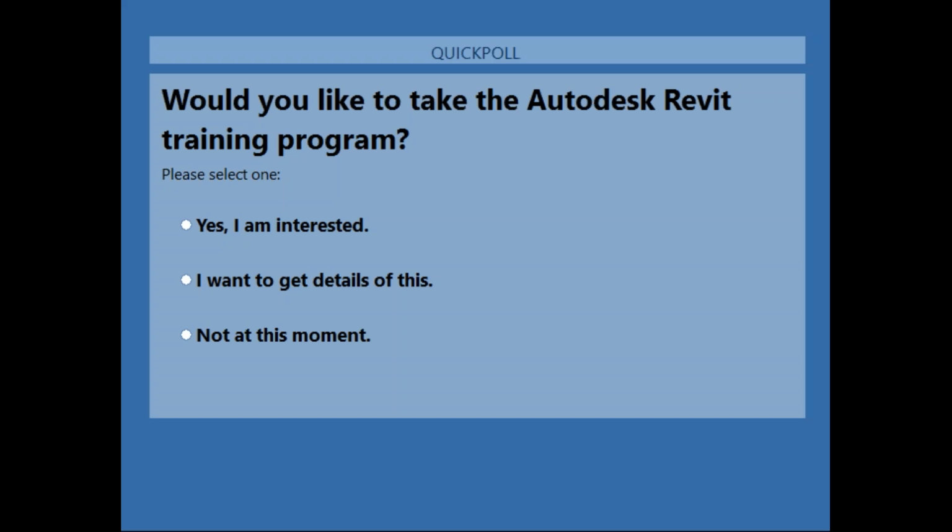In Revit, you only go to the filter, change the hatch to another hatch, or the color fill to another color fill less intense for the city, and you just do it only once. And because you have a view template, it will apply to the entire project documentation, and the change is going to be automatic for everything. If you do it in a 2D environment, it's probably going to take a good 2 or 3 days to do the changes. In Revit, it's going to take probably 2 or 3 minutes. I hope that answered that question.